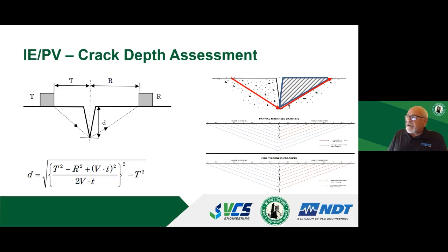And we also assess crack depths with this equipment. And there's a relationship to the distance from the energy source and or the distance from the sensor, the receiver, relative to the depth of the crack. And sometimes we will hold the energy source in the same location and move the sensor away 6 inches, 12 inches, 18 inches, or hold the receiver constant and move the energy source away, again, 6 inches, 12 inches, 18. And we record this information and get some general depths of cracks. A lot of times our crack depths are reported, say, in the 0 to 3 inch range, the 3 to 6 inch range, or the greater than 6 inch, which does help compared to looking at a crack, wondering how deep it goes. It does give you a little bit more information.